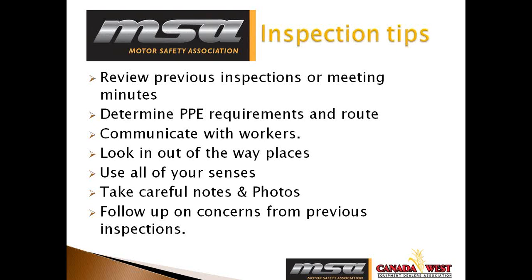And you want to take notes and possibly photos. You want to get some good notes about what you found, as well as perhaps where you found it if it's a large facility. So you may find that flashback arresters are absent on oxygen and acetylene torches. But if you're inspecting a building that has 3 different sites or sheds or storage areas, and they have many different oxygen and acetylene tanks, well, it would be a good idea to indicate where you found that so that